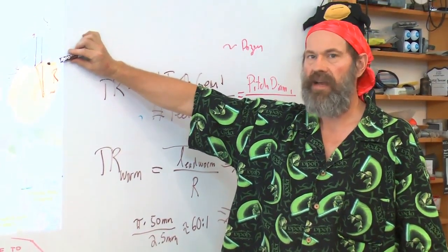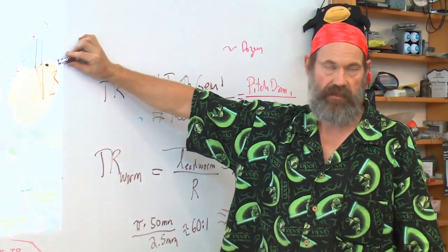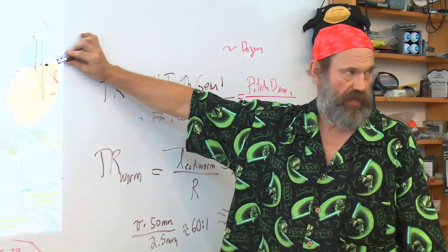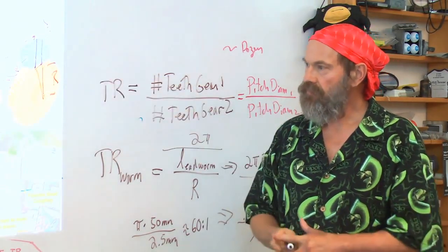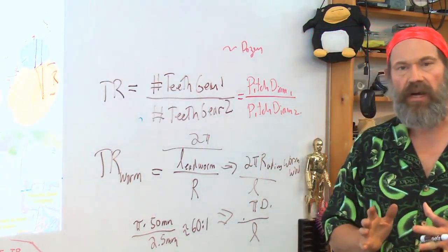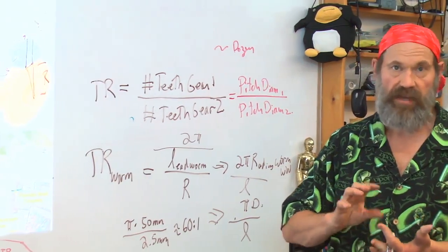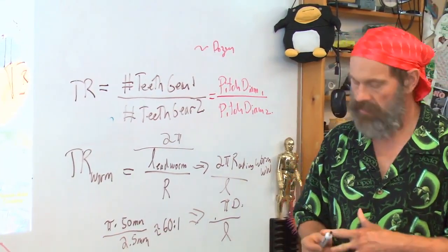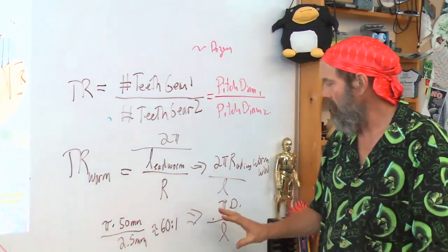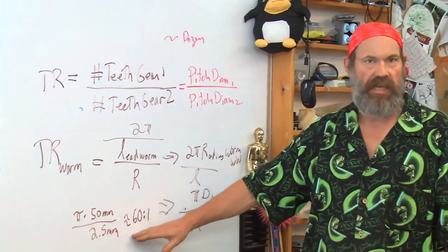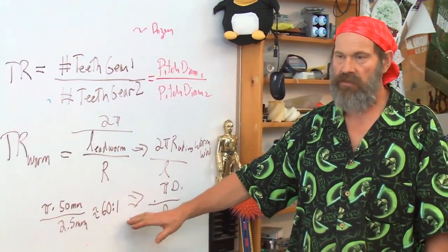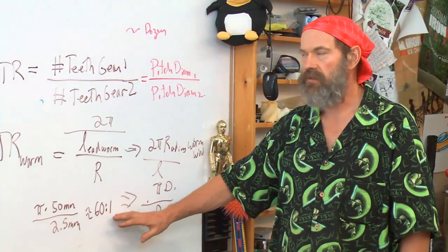This is also not back drivable. This gets back to the lead screw question and the ramp and the friction angle we talked about. This gets back to the question in a gearbox. If it's very high efficiency, it's back drivable. I can do it in one stage. I don't have it very high efficiency, but it's very low cost.